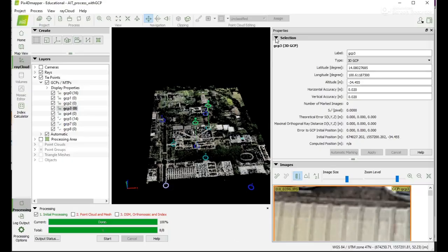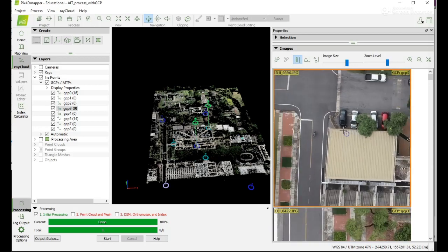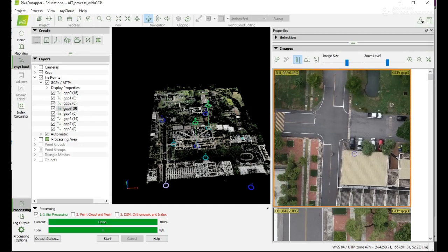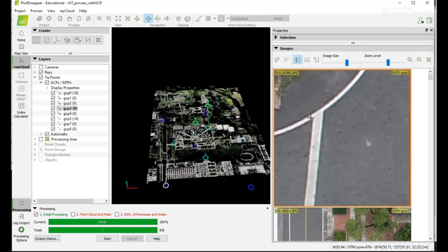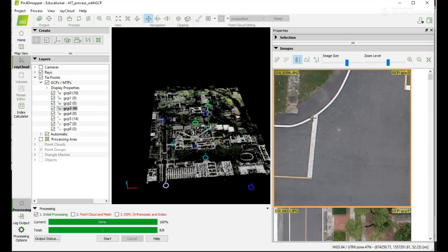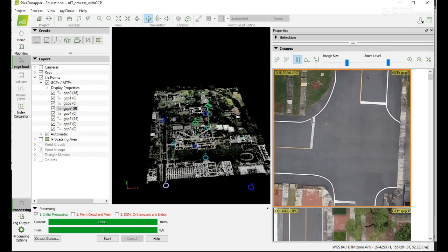Go to Pix4D. And how do you find what the GCP is? So always keep a sketch. So I know that this is the point, this paint marking. You can see, you can clearly mark. I know this point because I already did this processing twice, so I can easily identify the point, but